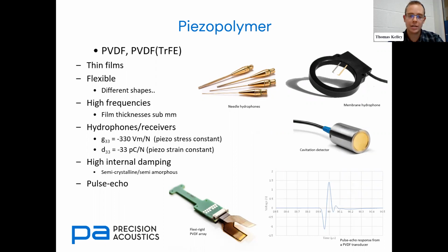It's got excellent piezo g coefficients, but it's not great at producing high levels of power or high amplitude outputs. So it's not a good choice for high power ultrasonics or for transmit only applications.